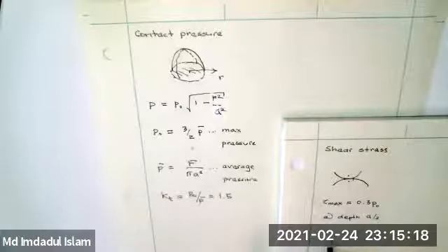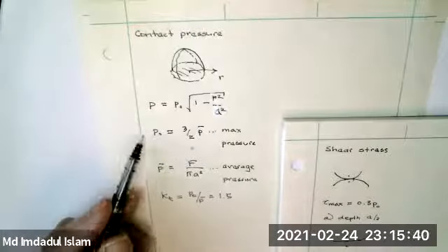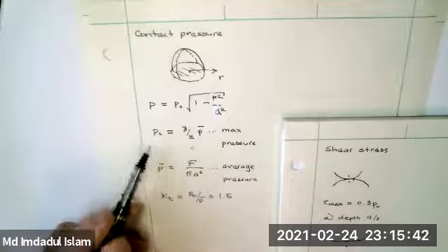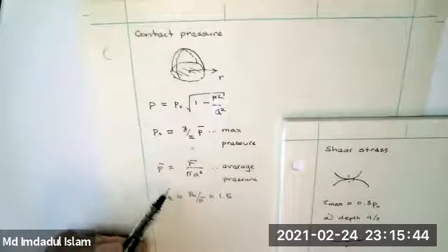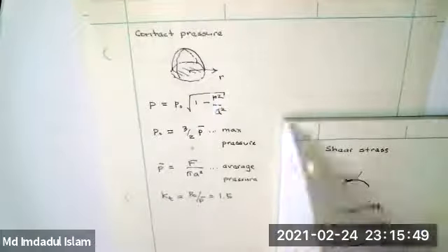So this is the contact region. This is 2A, and this depth here is A upon 2. So it's near the surface. A is small, so A upon 2 is even smaller. And that's where the maximum shear occurs. That's where yielding is going to occur. I can rearrange these to give you some sense of how this P naught behaves by substituting for A.